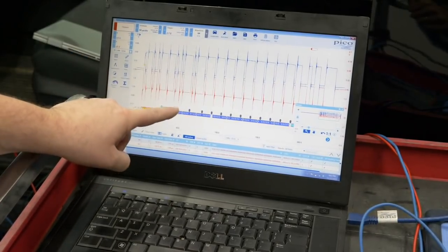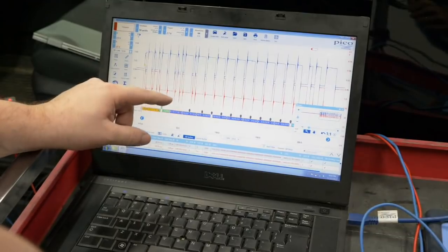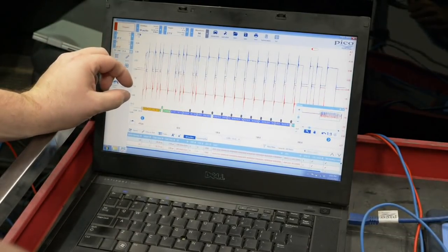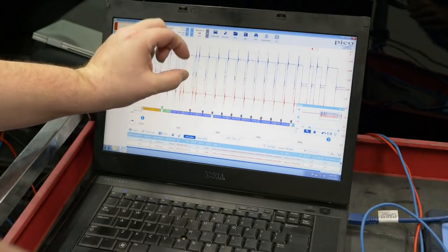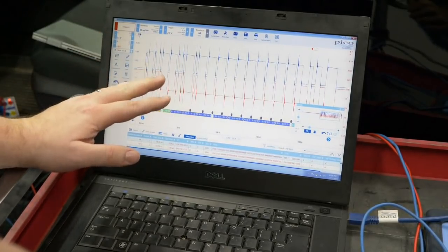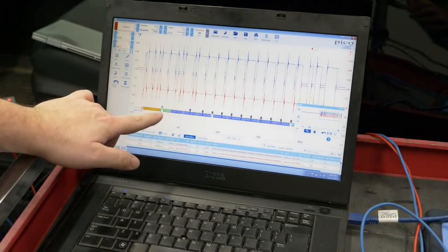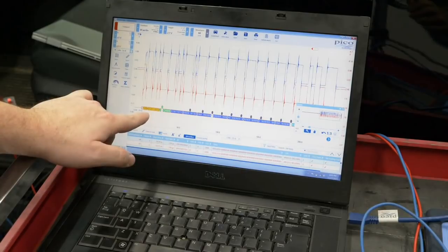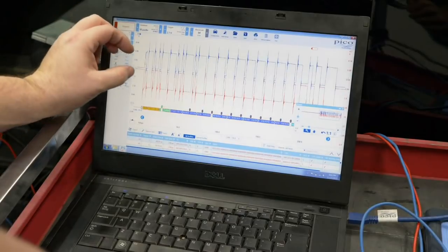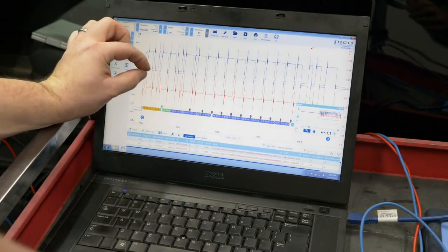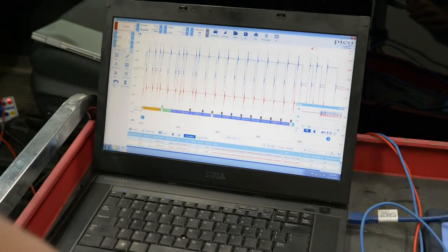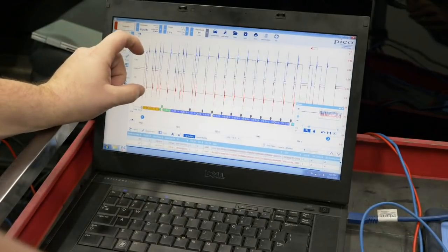The reason this network is designed this way is that when you're in recessive state, if somebody else sends out a dominant state, it will override that recessive state. So when we're doing this very first part, it's called arbitration. Basically it's sending out a bunch of data, and it's expecting this to be zeros, but it's also listening at the same time it's sending that data out.